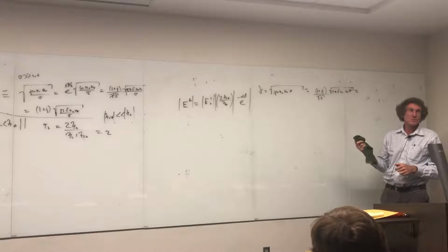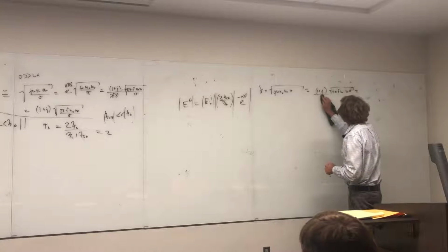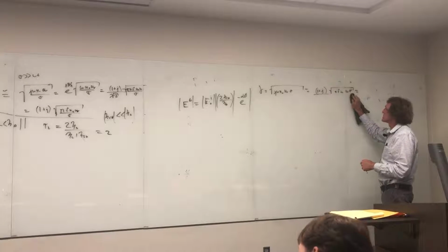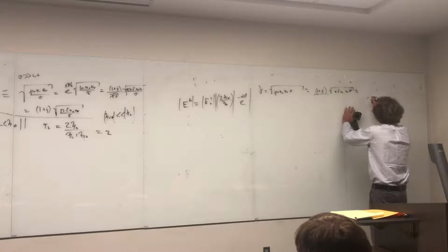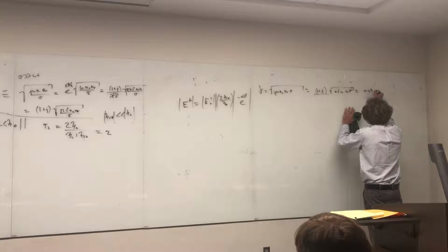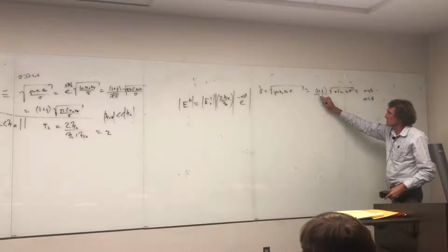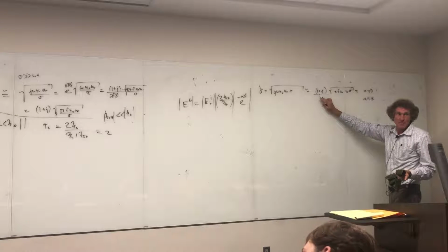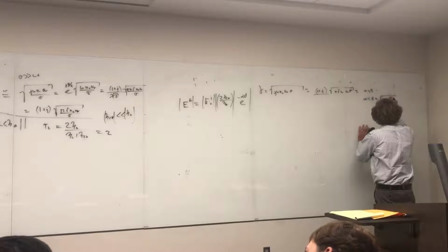You notice the square roots of 2 cancel, correct? So get rid of them. I'm going to get rid of this one right there and there. And now I have pi f mu sigma times 1 plus j. What it means here is that alpha plus j beta implies that alpha is beta, if you can see this. The coefficient of j is beta, the coefficient of 1 is alpha, right? And in both cases, they're equal to the square root of pi f mu sigma. I'm going to leave it as that.